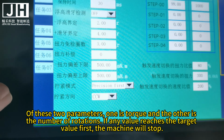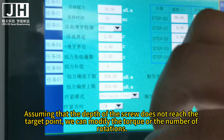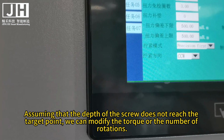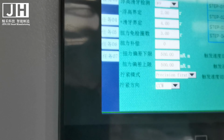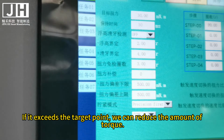If either value reaches the target value first, the machine will stop. Assuming that the depth of the screw does not reach the target point, we can modify the torque or the number of rotations. We can increase the torque. If it exceeds the target point, we can reduce the amount of torque.